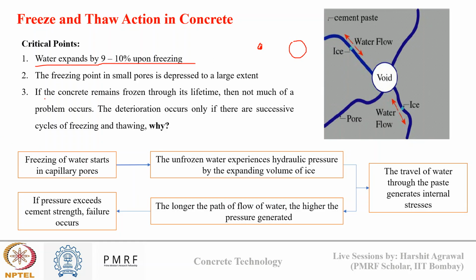And if the concrete remains frozen throughout its lifetime, then it is not a concern. The deterioration only happens when there is cyclic freezing and thawing action. So it is not just freezing of concrete which will cause degradation. It is the freezing and thawing effect that causes degradation in concrete.